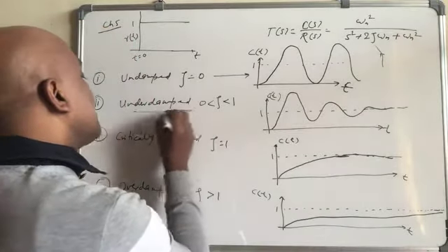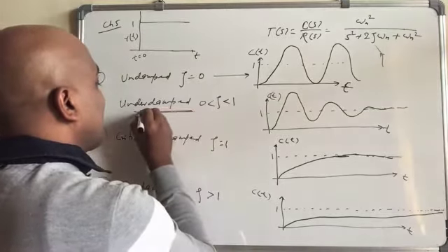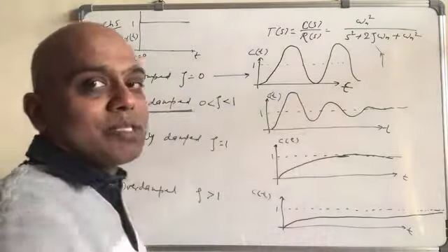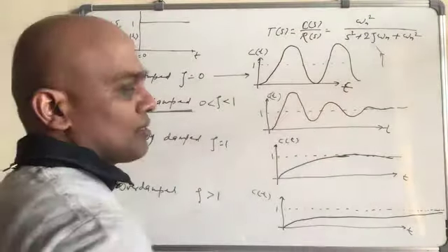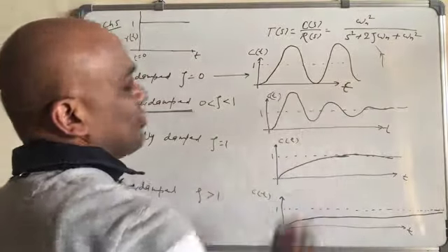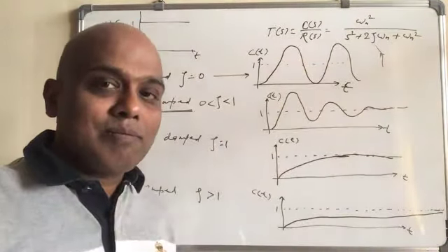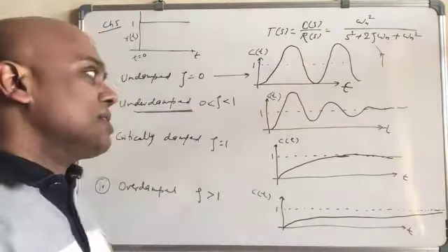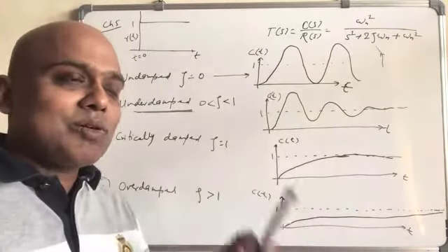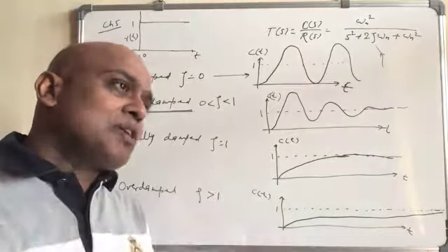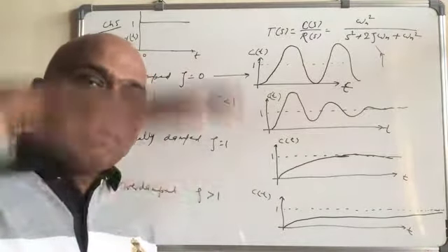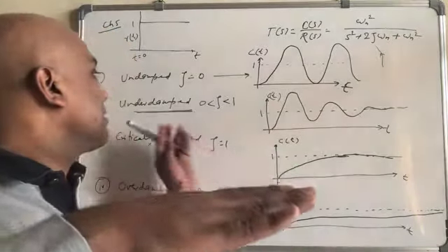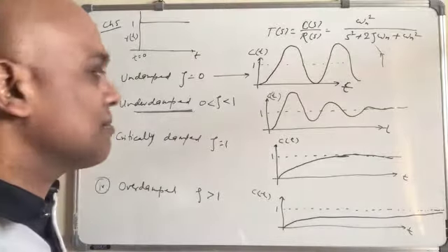So the underdamped condition is very important, and this is widely studied in control systems. What is the advantage? The advantage is response time. Very quickly you can reach the response. There may be a little bit of oscillation, but still you will be around there. And hence in a motorcycle, for example, that's a passive vibration control, by a spring mass damper system only, but you have an underdamped condition there, so that the response to a pothole goes a little bit like this and then settles, goes like this and settles, right? So this kind of action is basically underdamped only. That may sound familiar to you.